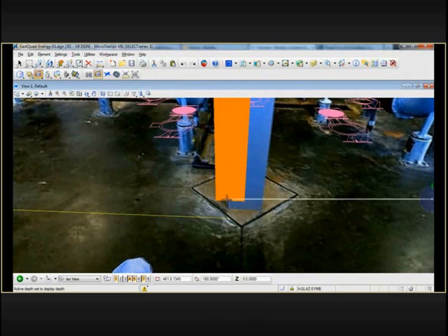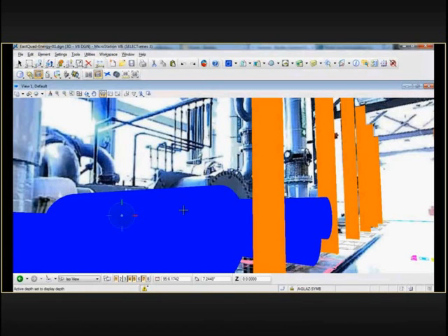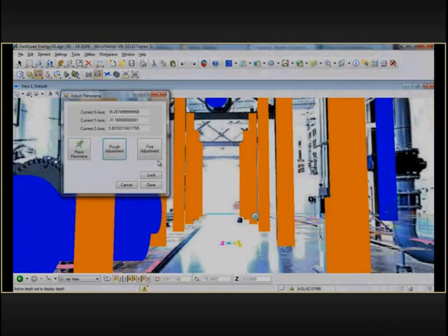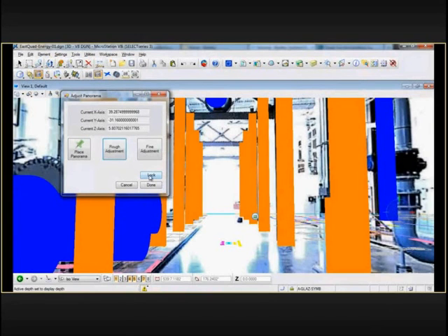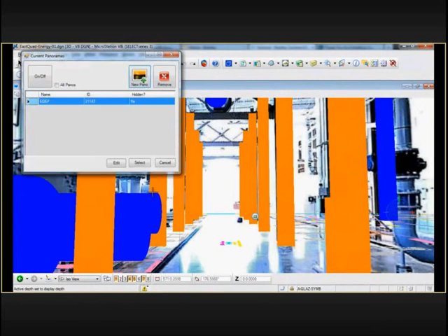So upon doing this 6 to 7 times, the user would then be able to click the Align button and the photo panorama would shift into place. So again, seeing that point on the model to the point in the image. So once the user has completed that, they can lock the view down, lock the panorama into place, and then go back to the main UI. You'll see that then the cell is populated in the grid with your panorama, its ID, and its visibility.